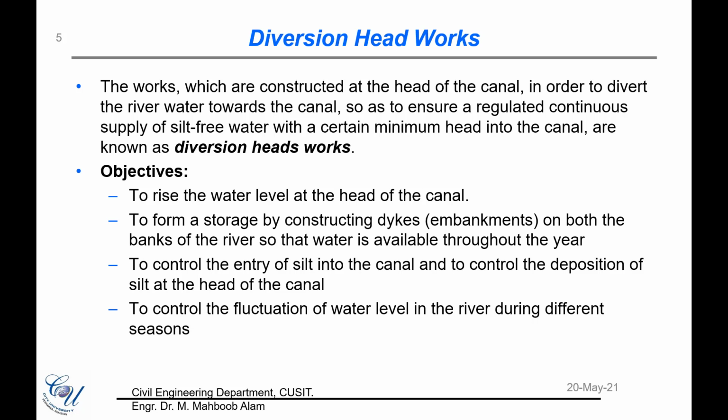Diversion headworks are basically structures which are used to raise the water level so that we can then push water towards a particular canal or channel. That water can then be used either for hydropower electricity production or for irrigation purposes. The main purpose, in addition to increasing the head and diverting the water, is also to provide water in a continuous regulated way.